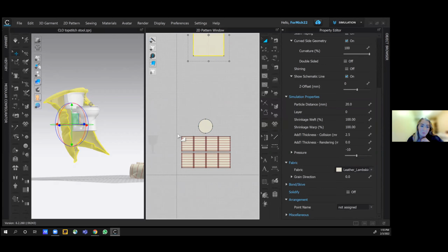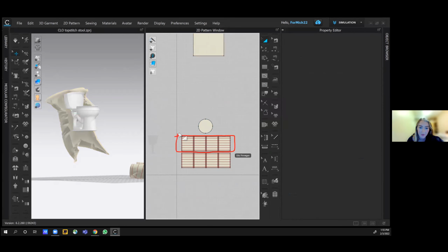And if you were making them inflated, you would add positive pressure to the top one and negative to the bottom one, and they stitch and stay together. No, that sounds correct, but I'm also just learning the software, so that is a hot tip. Yeah, I did the same thing. You just have to be careful: I think you put -10 pressure on one side and then +10 on the other piece.